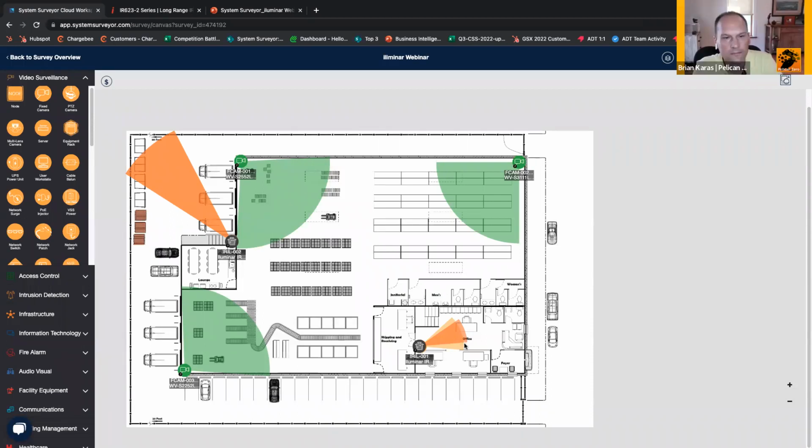Yeah. And where we mentioned on the outdoor ones you might want to overshoot the field of view a little bit, again on the indoor ones, in a lot of these environments, you get a lot of light bounce that helps you. Going a little bit narrower on the field of view is fine, particularly if it's a budget-oriented installation and you don't want to go for the wider field of view one or the longer range one. Usually undershooting it there is going to be more than sufficient.